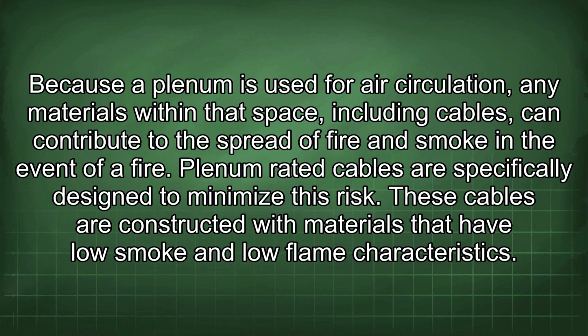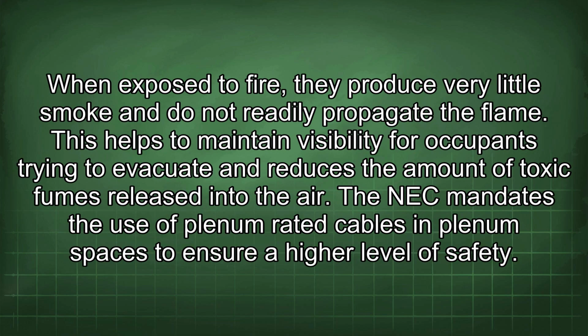Plenum-rated cables are specifically designed to minimize this risk. These cables are constructed with materials that have low smoke and low flame characteristics. When exposed to fire, they produce very little smoke and do not readily propagate the flame. This helps to maintain visibility for occupants trying to evacuate and reduces the amount of toxic fumes released into the air. The NEC mandates the use of plenum-rated cables in plenum spaces to ensure a high level of safety.